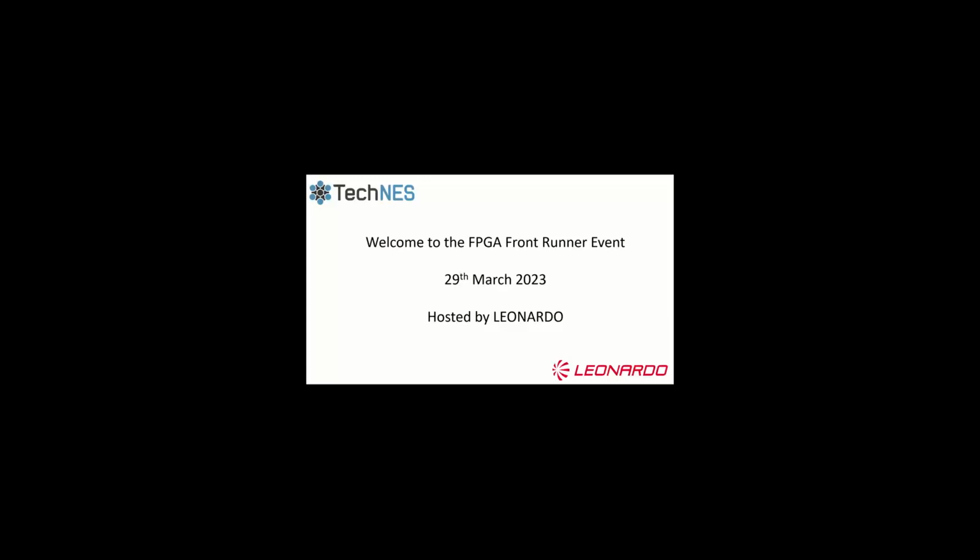Slightly more complex example shown on the bottom left-hand side here. This is where we've taken our IP core and integrated it with a larger design. So we might have a skeleton design or even a real implementation that we've got running on some hardware already, and we want to drop our newly generated IP core in that and map it into our existing AXI infrastructure, so it's tied into the external memory interfaces, that sort of thing. Again, we can use the same AXI bus master IP that comes from MathWorks to allow access to that core and all the other external memory as well, straight from MATLAB over JTAG, UART, or an Ethernet interface.